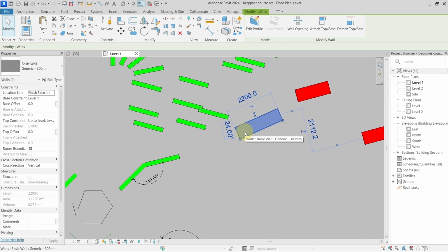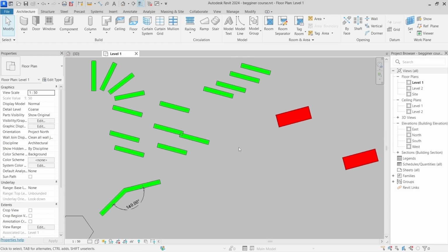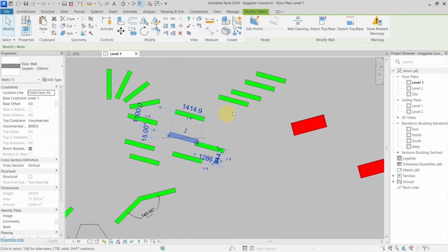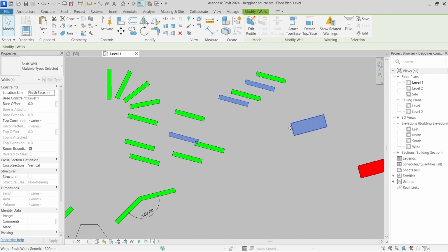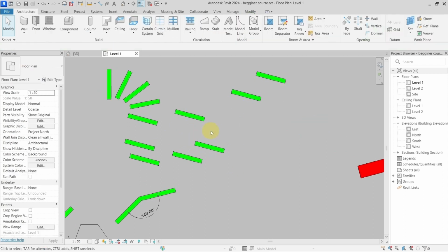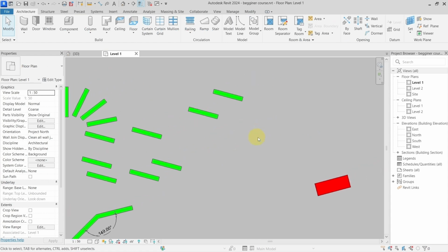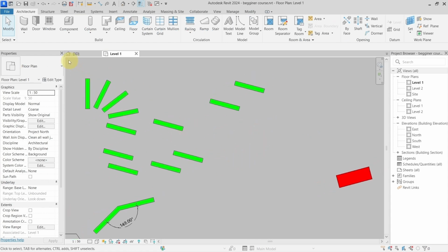So if I select my wall and I go with my EH shortcut, you can see that it disappeared from the view, but I do not see any bluish rectangle here telling me this is the temporary view. So you can see that I was able to hide this, but this is not temporary, this is permanent. So if I continue, select again, and go with my EH shortcut, I am hiding this, but permanently. It's not temporary because I do not see this bluish rectangle around here.